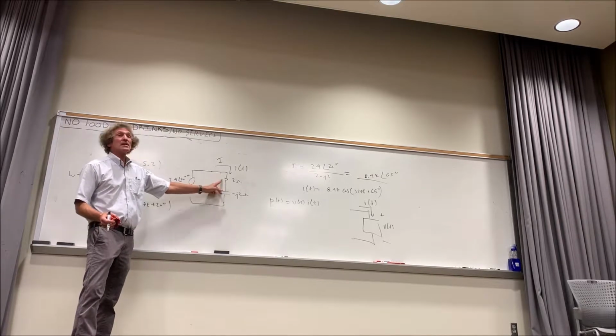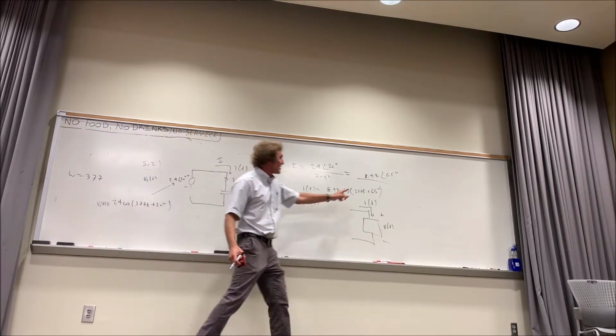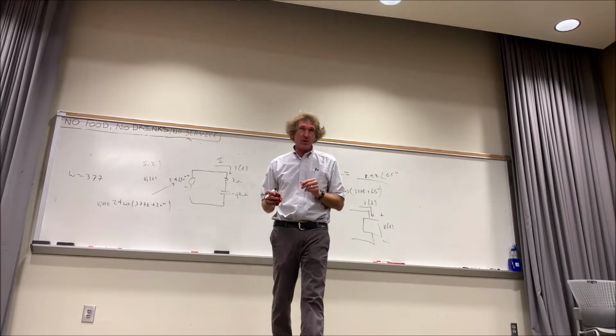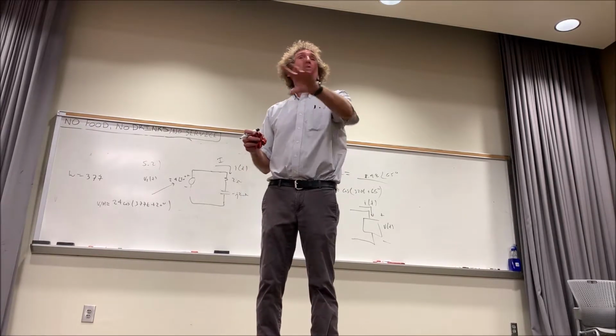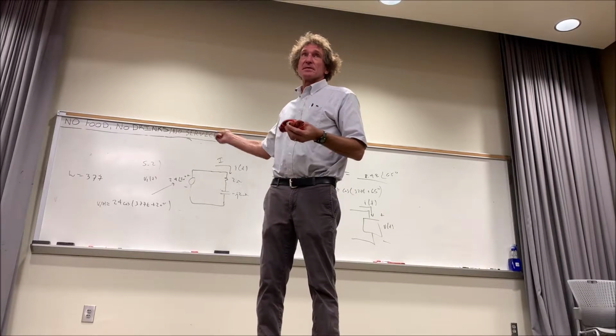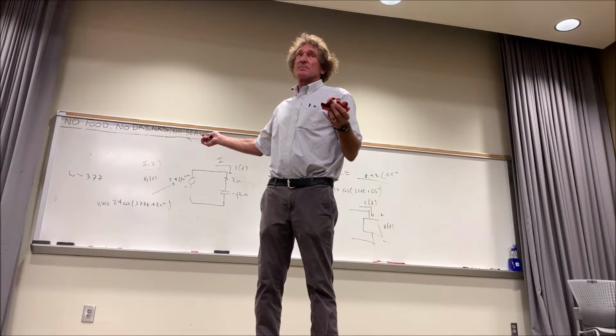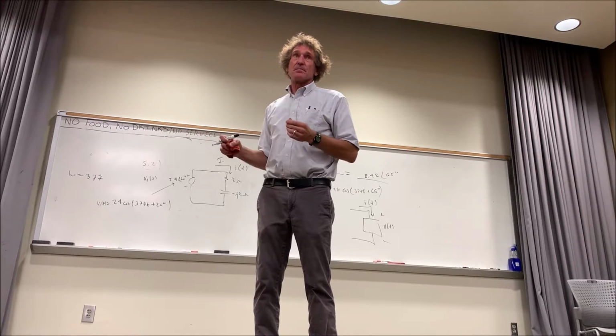One half times the element's value of resistance 2, right? Times the peak value of current squared. What's the peak value of current squared? 8.48 squared. Follow me? That's all the power, average power dissipated, but it's not the instantaneous. Instantaneous would be voltage times current. That's it. That was something just to get you familiar with the differences.